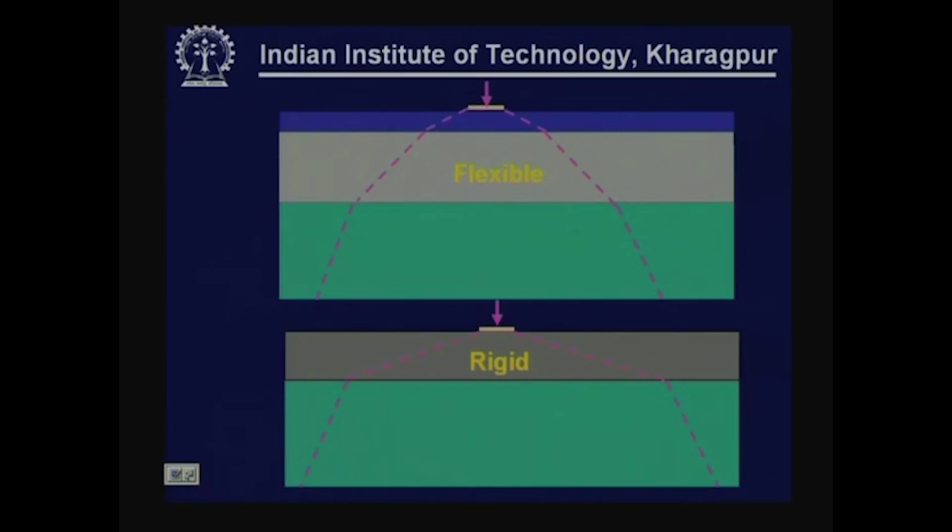normally we differentiate these two types of pavement in terms of their load spreading capability. The materials that we use and the layers that we provide in flexible pavements are in such a way that normally the upper layer is stiffer compared to the lower layers. As a result the load spreading capability gradually goes on decreasing. The load spread has to be done in such a manner that in each layer the stresses that are induced should be less than what can be handled by that particular layer.